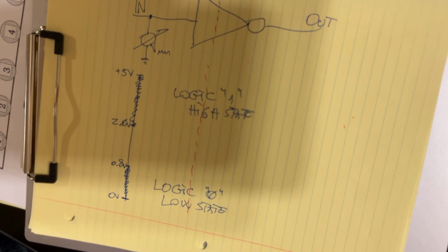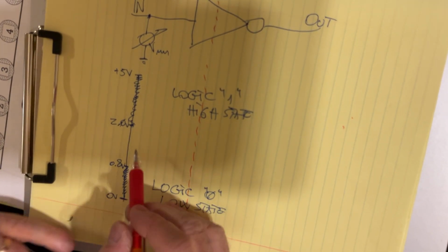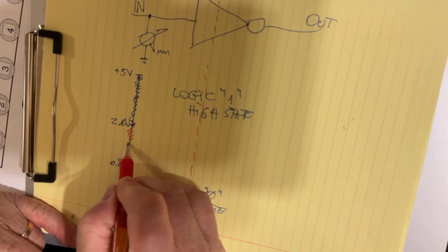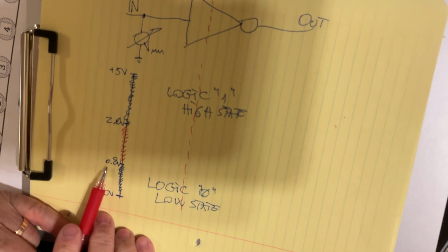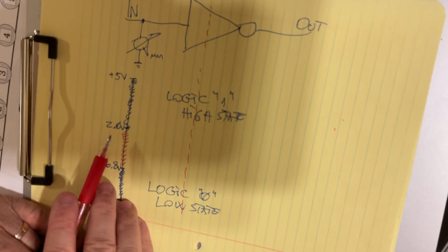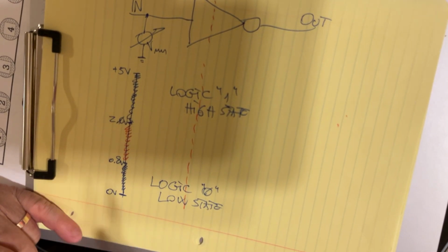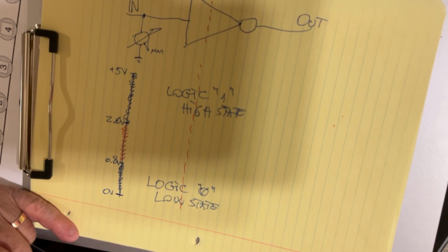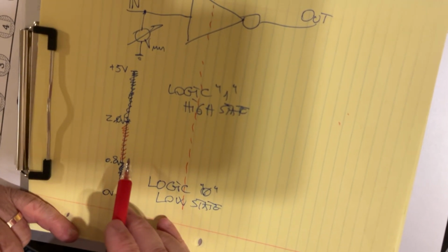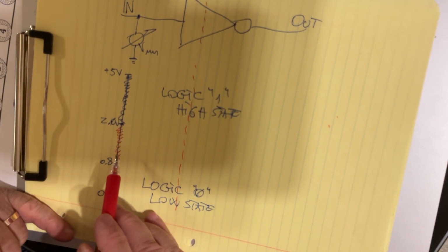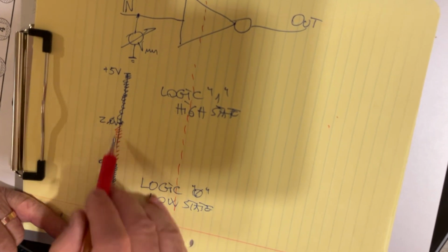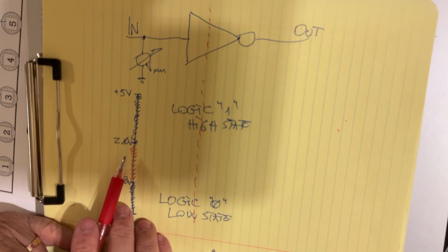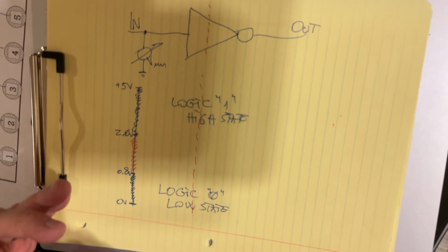What about the voltage of about 1.9 volt we measured before? Whatever is here between 0.8 volt and 2 volts is a kind of forbidden state. But you cannot prevent the circuit, like we measured before, from showing you values in this range. When you measure anything between these two, bigger than 0.8 volt but lower than 2, this is considered a kind of confusing state.